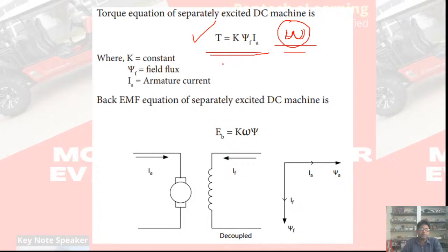But for induction machine, squirrel cage induction machine, this analogy is directly not possible. You see, there two components are there. If you remember the torque equation which we have established, that is psi rd into isq minus psi rq isd. There is a vector summation of two flux, and another is opposing, negative. So it is coupled. The torque equation is coupled with the two flux, but I have to decouple.